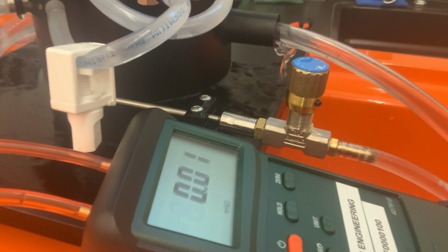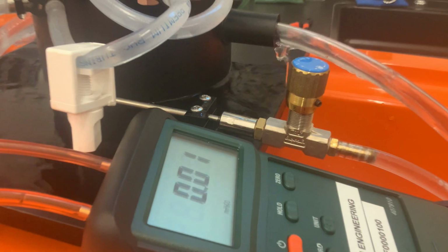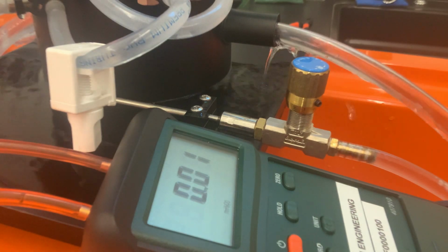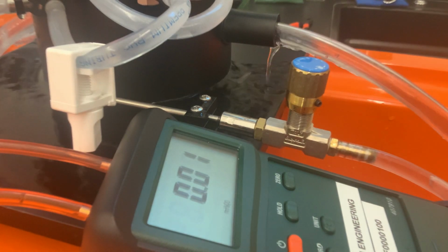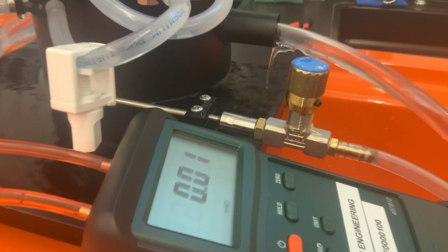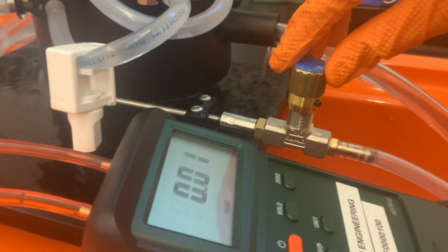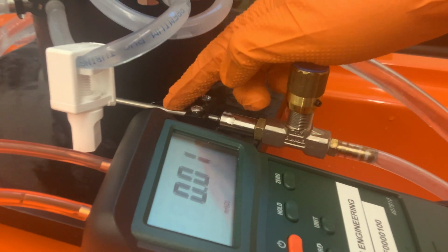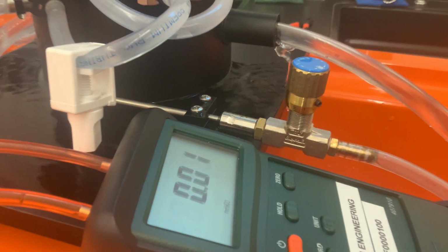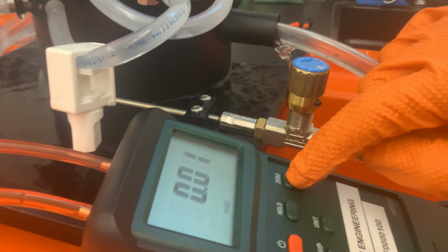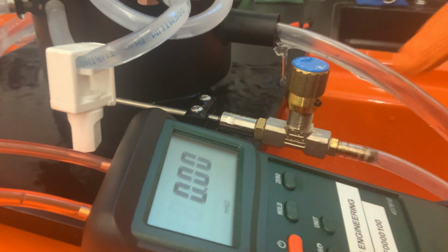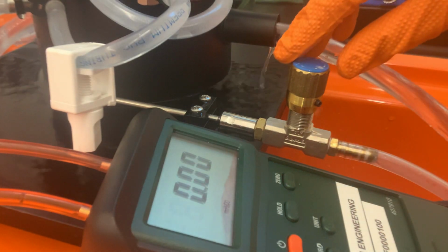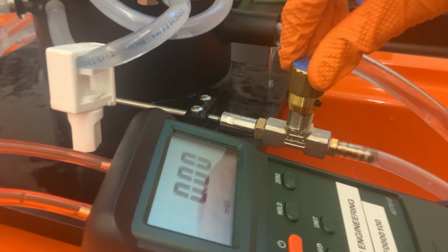So the data collection for low flow rate, when the water is coming through the constant head tank into the pipe system here, the procedure is the same as the previous one. I have closed my valve, so there is no water flow through the pipe that we're testing. At this point, I'm going to set my manometer to 0, and I'm going to open the valve.